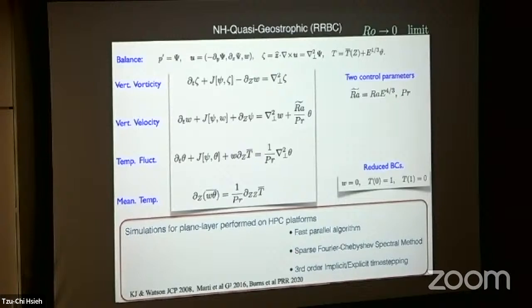Okay, so now we're going to take a tour of what the fully nonlinear solutions give us. We want to solve these equations, and to do that, we're going to have the Rayleigh-Bénard setup. We're looking at a plane parallel model with bounded plates at the top and bottom, separated by a non-dimensional distance of 1, and we're going to have periodic sidewalls. So it's a periodic layer, and there's still an effort to solve these things. So we have an algorithm. Because we're periodic in the horizontal, we can use a Fourier decomposition.